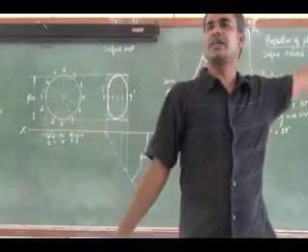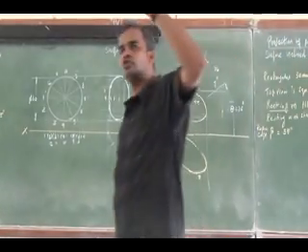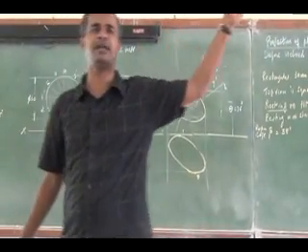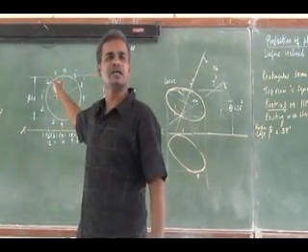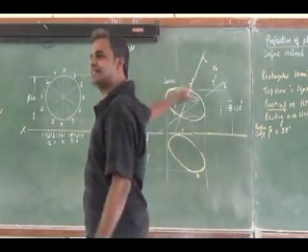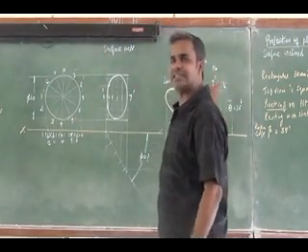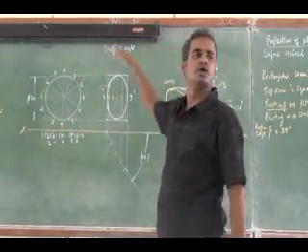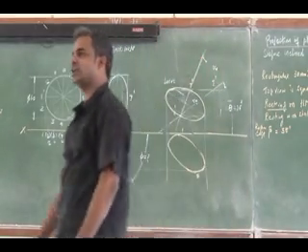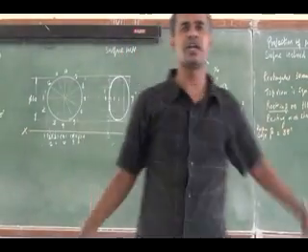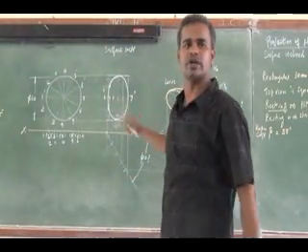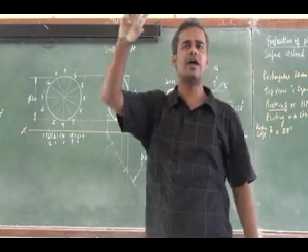Right? So in the previous 3 problems we used only one surface inclination, one apparent inclination. In this problem, we have used two surface inclinations. The second surface inclination we cannot use as it is. We have to find the apparent inclination for that. Then along that apparent inclination angle, you have to reproduce the front view or top view, depending upon the problem. Is it clear? Do you have any clarification?